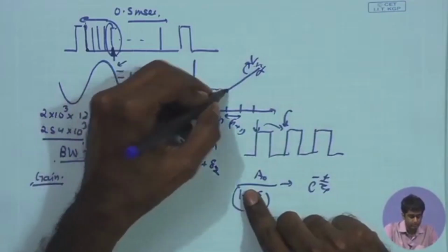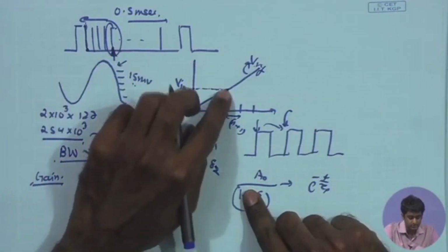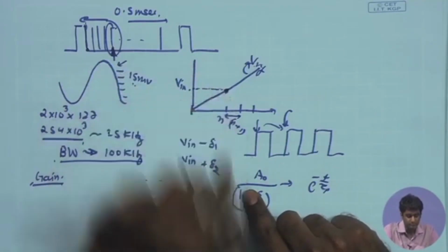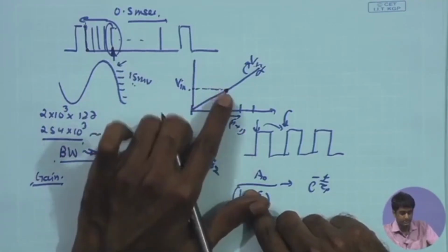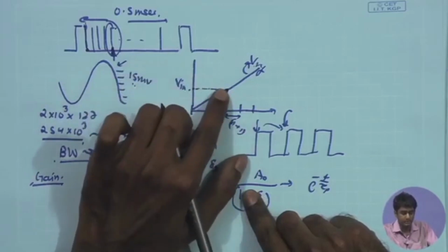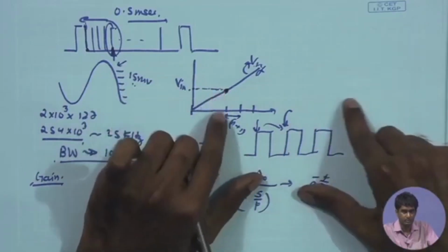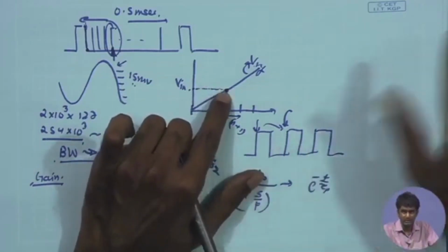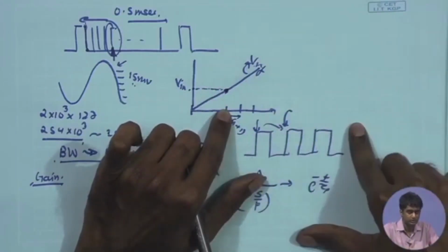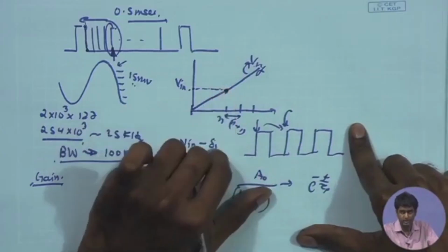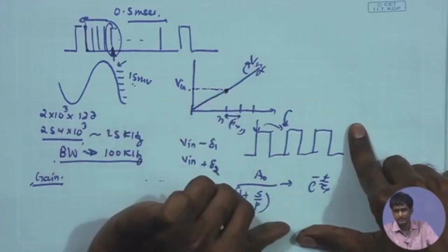So if the Vref approaches Vin just before the nth count, the counter may miss this falling edge of the comparator. Ideally the comparator will go down at this point, but of course the comparator has some finite delay, and the control loop which is supposed to set the counter off also has some finite delay, so it may end up missing this transition.